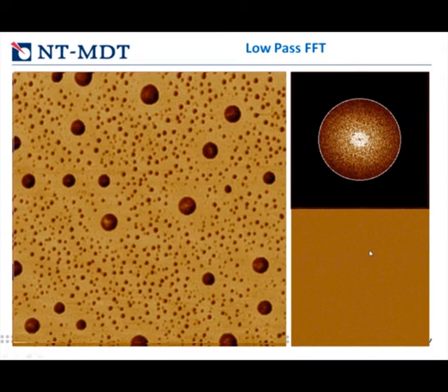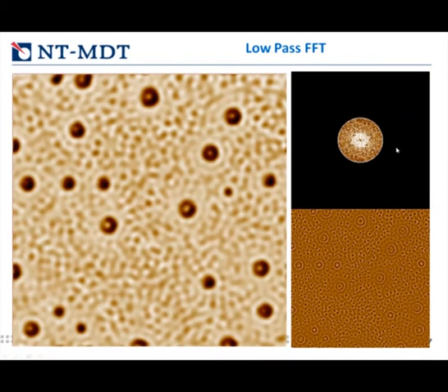You'll see that really high frequency noises have gone. But again, if we use this filter too much, meaning that we decrease the band of the filter too much, we'll start to see that the image has lost plenty of details, and in the difference between the result and the original image, we see that the objects really start to appear.